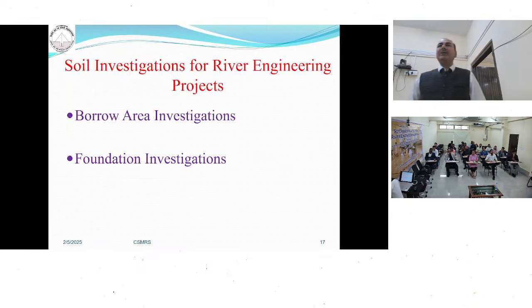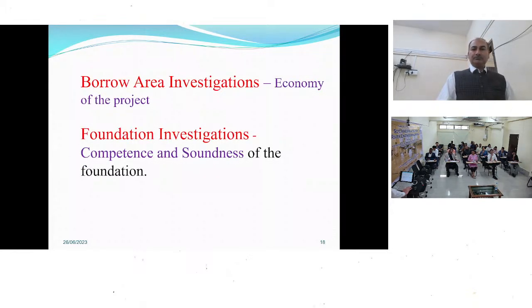So when we are choosing the material, we choose the material that fulfills all these requirements. For a dam or any river valley project, we carry out two kinds of investigation. One is the borrow area investigation. Second is foundation investigation. Borrow area means the area from which we take the samples. We take the material, which is called the borrow area. In the case of an earthen dam, we collect soils.